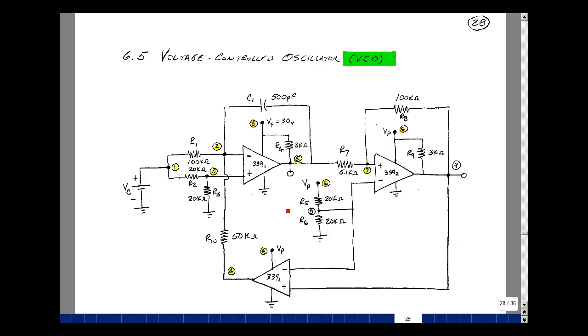This first circuit over here, we've got feedback to the minus terminal. So this comparator looks like it's being used as an op-amp. We'll take a look at that in just a little bit. Here I've got the feedback going to the plus terminal, so that's positive feedback, and this is one of our hysteresis loops. And then here I've got a comparing of two voltages with no feedback around it, so this must be used as a comparator also. What else can we say about the schematic as we look at it?